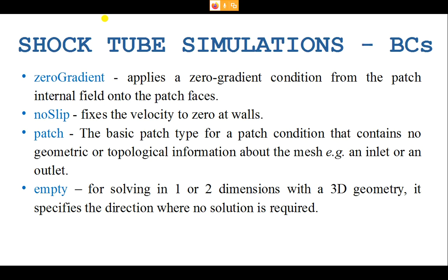Once we do this initialization, we can start the solver by saying that at time t equals 0, you can start solving. With respect to this transient simulation, you might find that the molecules present on the high pressure side will start moving towards the right side, forming a normal shock and expansion waves.